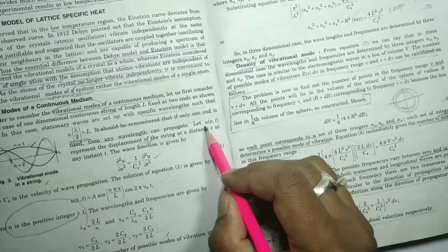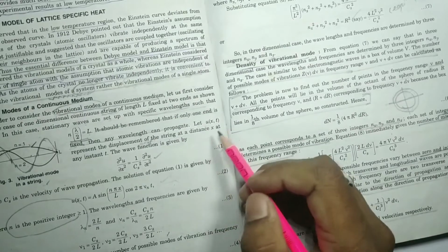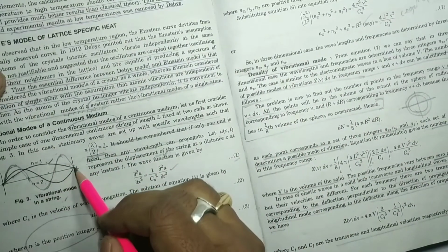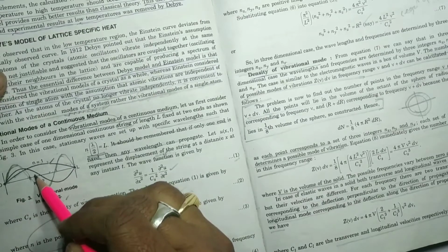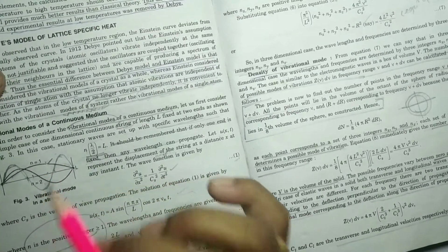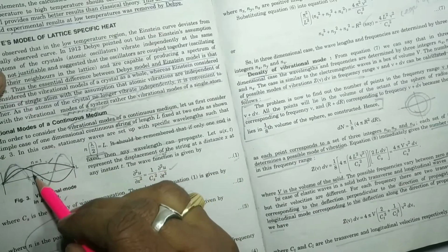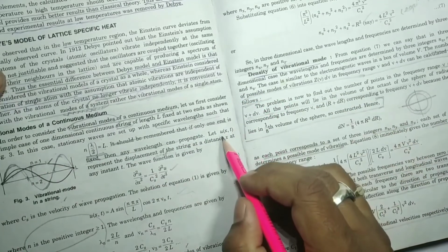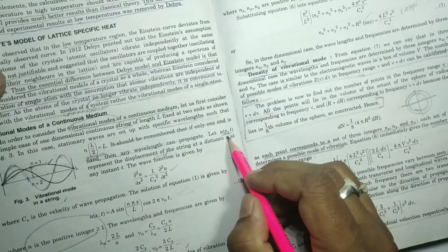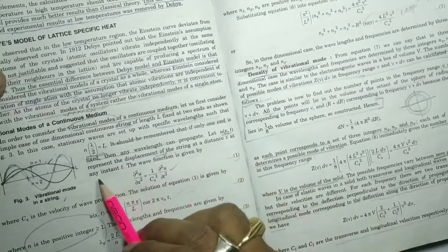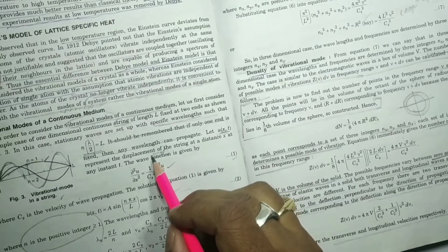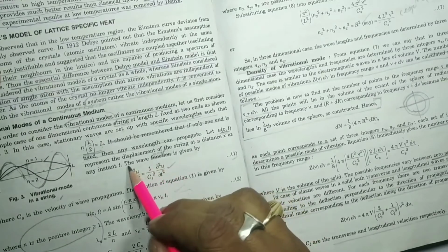Now at a particular time, at a particular point, what will be the displacement when it is vibrating? Here x equal to 0, and this is x equal to L. At a particular x, at a particular time, for a particular frequency, what is the displacement from its mean position, up or down? That is nothing but u(x,t), which represents the displacement of the string at x at time t. The wave function has been written mistakenly, so you just write the wave equation.